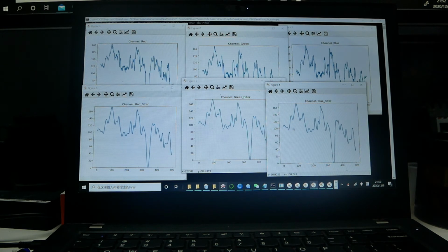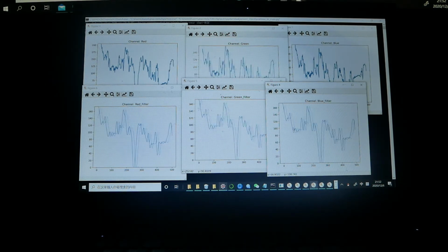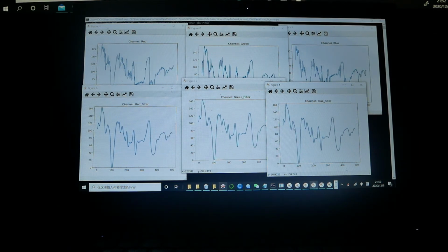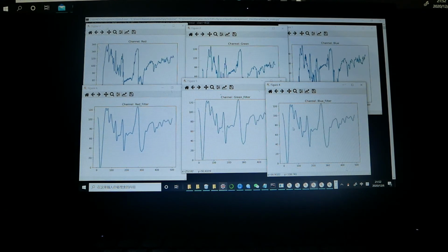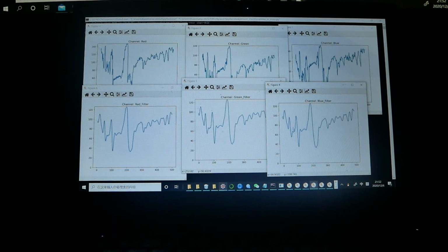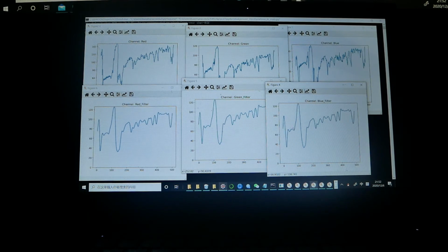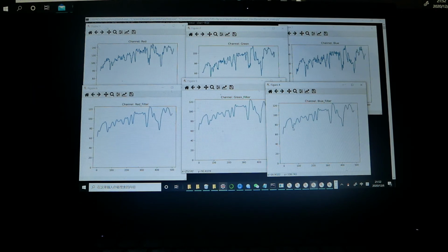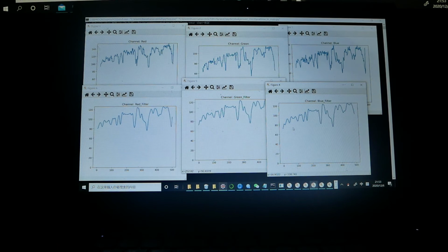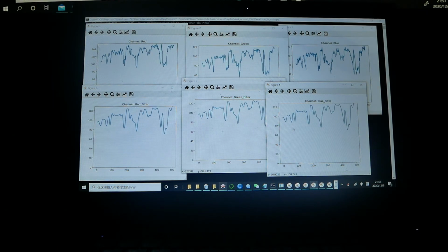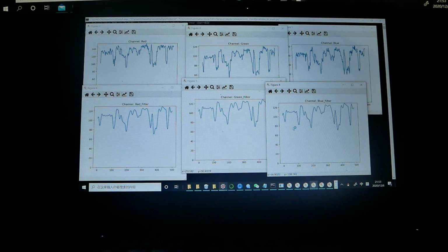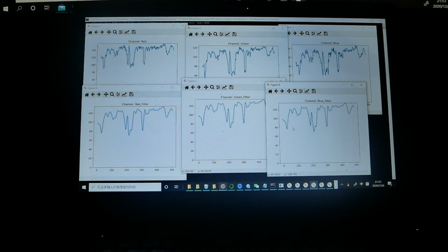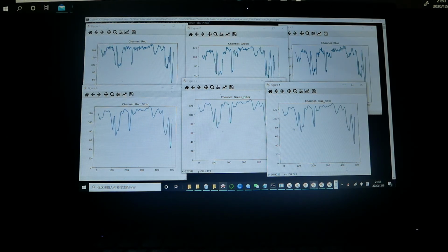That is, when I turn the light off, as you can see, there is a dramatic decrease followed by a recovery. The camera is trying to adjust the gain to restore the RGB value to the previous one. So it means that if we apply brightness-controlled brightness adjustment, there will be some problems. But this webcam works very well in phase-controlled brightness adjustment. Later, you will see that.